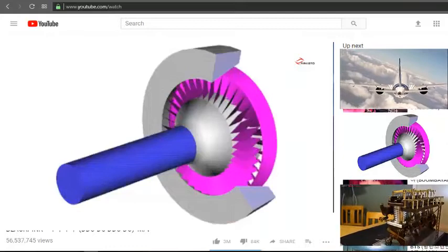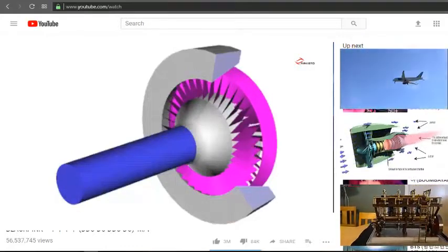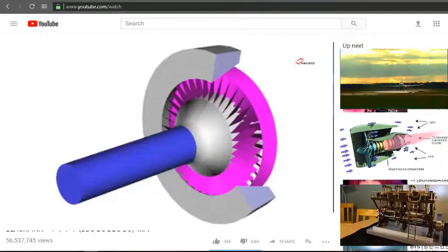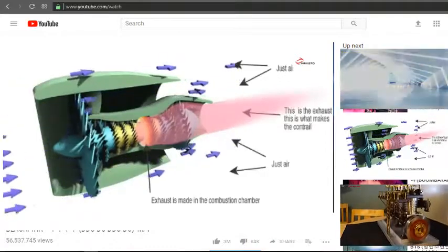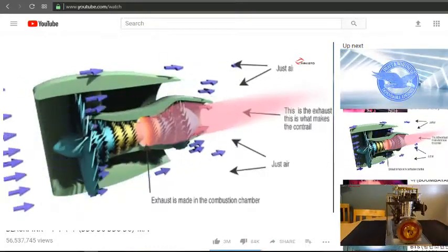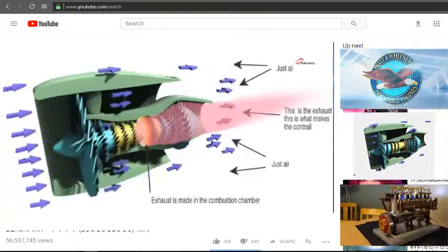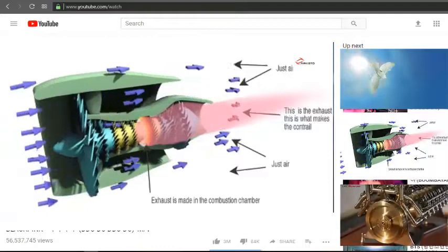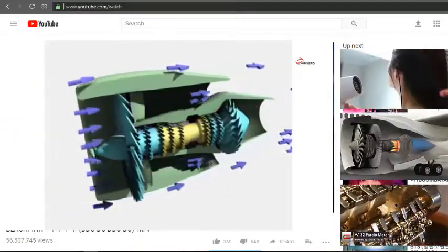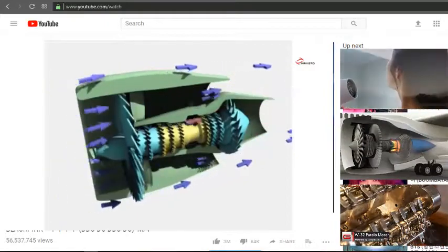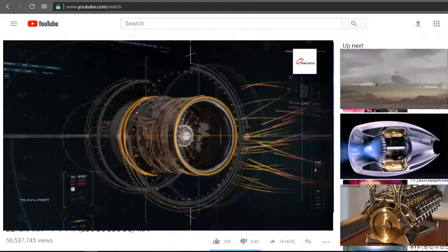Turbine. The high-energy airflow coming out of the combustor goes into the turbine, causing the turbine blades to rotate. The turbines are linked by a shaft to turn the blades in the compressor and to spin the intake fan at the front. This rotation takes some energy from the high-energy flow that is used to drive the fan and the compressor. The gases produced in the combustion chamber move through the turbine and spin its blades. The turbines of the jet spin around thousands of times. They are fixed on shafts which have several sets of ball bearings in between them.